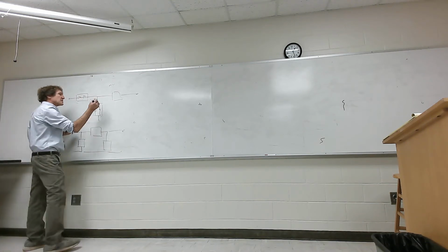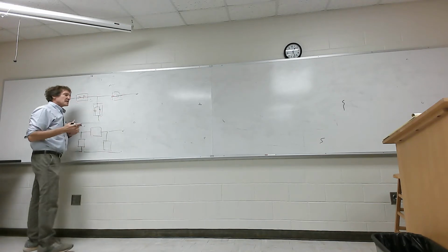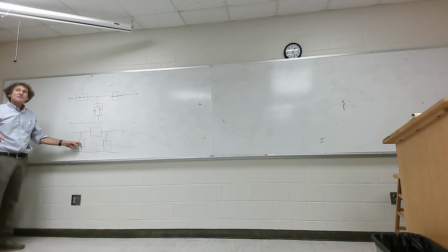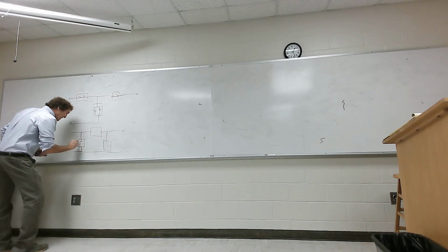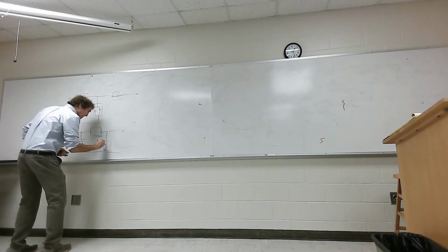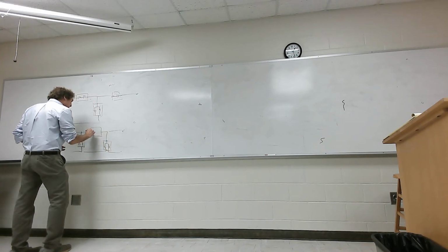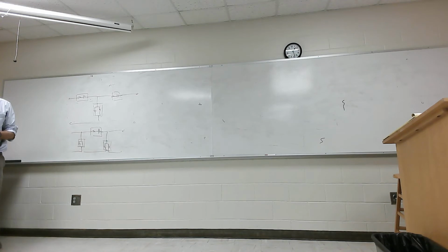Over here you're going to have the same thing as this. It'll be a series LC. Over here, what happens? Parallel elements, you always want the impedance to go to infinity at resonance. These are going to be parallel, or they call them tank circuits, I think. I don't know if you've heard that expression. And this is going to be a series. Just get familiar with the way things are going to be laid out.